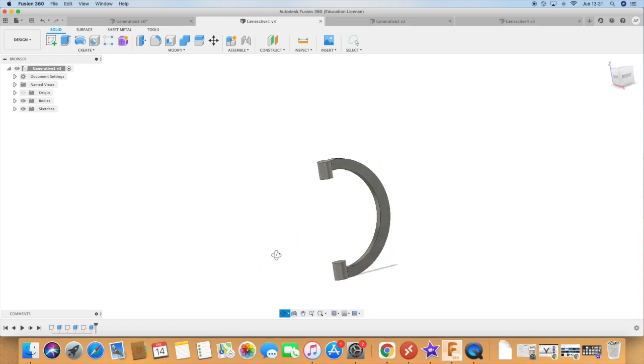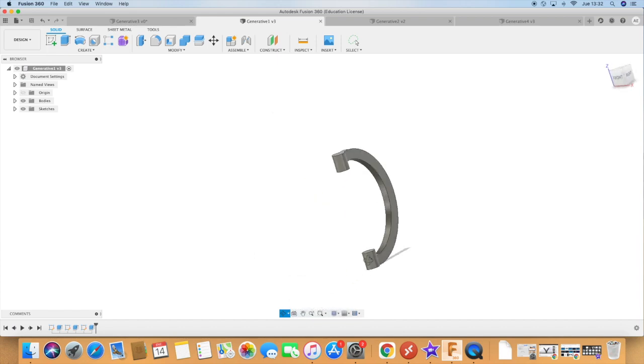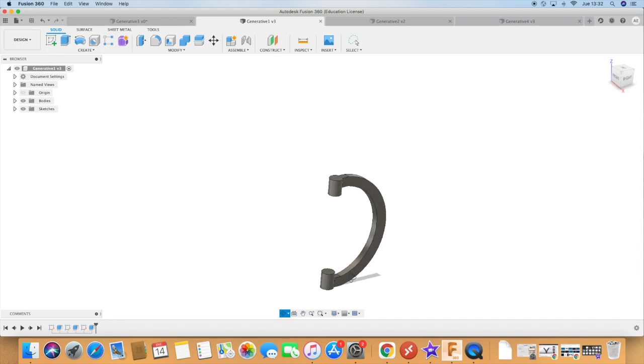So let's suppose that you have some sort of beam that has to go through here horizontally, and yet there's 2 points, in this case these two cylinders, that must be connected one to the other one, and there's a force being exerted on the top one, and maybe the bottom one is fixed to the ground. There we go, my mouse is back. So you need a shape that more or less looks like this. And at the same time you need to optimize for the mass, as we've done before, because that saves money. And for that purpose we're going to use topology optimization initially to see how that looks like.